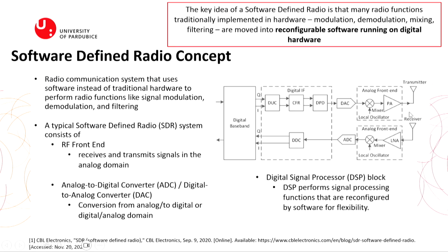So you can see transmitter, receiver, power amplifier, low noise amplifier. Of course, you need a power amplifier because you need to transmit high power, and the receiving power is very low, so you need a low noise amplifier to amplify the received signal to some desired level. And why low noise? Because you don't want to add another noise source to your received signal.